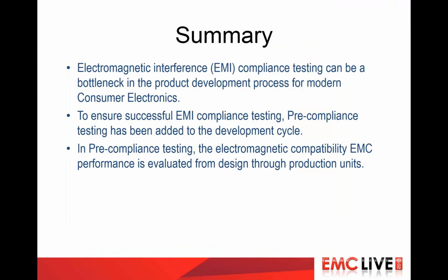So we'll just kind of do a wrap up here. Again, EMI can be a bottleneck to your process being completed. You're trying to get stuff to market. Time to market is critical. If you spend time looping around with a compliance house, you're losing time. So it's typically a worthwhile investment to do some pre-compliance testing. We do have tools that have the same measurement engine as a full compliance, so it gives you a good understanding of how the full compliance house is doing. It's a very inexpensive software license key to turn it on if you currently have one of our test sets.